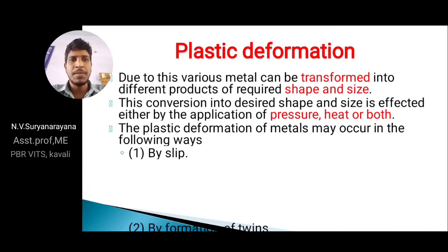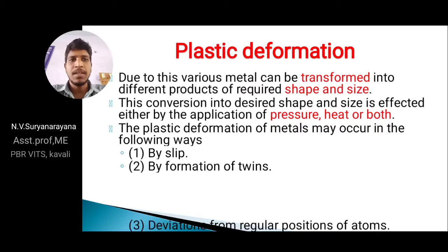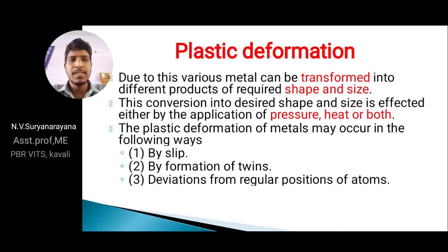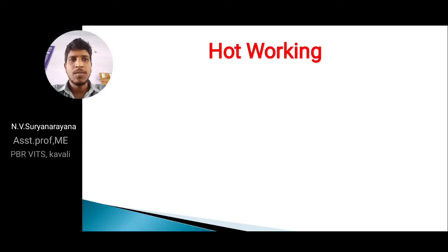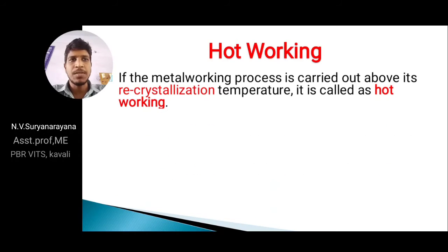The plastic deformation may occur by slip or formation of twins, deviation of regular positions of atoms, breakdown of structure. Finally, the structure, after exceeding the load over the plastic deformation, may fracture. First, coming to hot working.